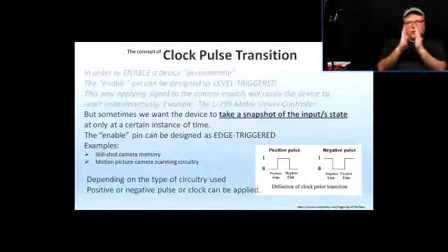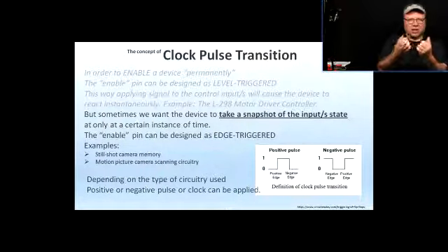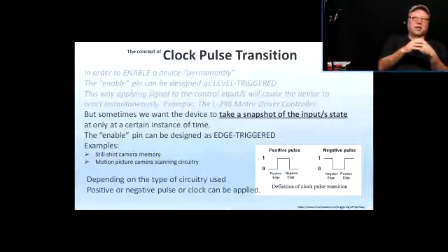If you have pulses that have a bigger duty cycle, then you're limited in the frequency of the clock, or how fast you want the clock to operate, by the duty cycle of that clock waveform versus the frequency. But if you narrow it as much as possible, then you can have a faster clock. Then you can have faster operating circuitry. You can have faster computers, faster cell phones, whatever uses digital circuitry.